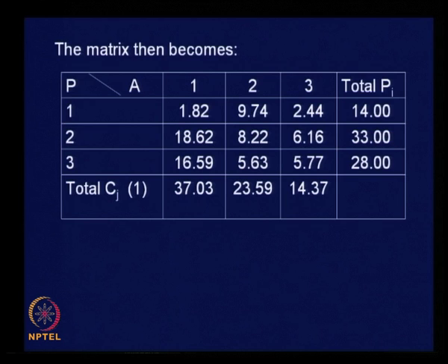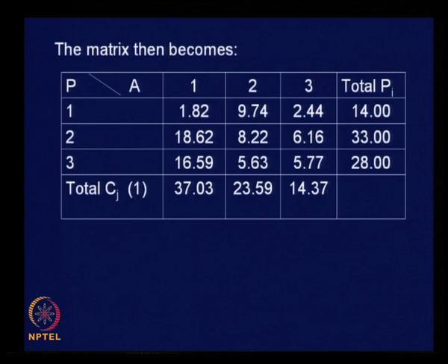Now what do we do with this result? Can we say that this distribution is acceptable? It is not, because the distribution process should not distort the basic values of trip production and attraction. Your zonal trip attraction values are distorted because of the distribution process. The reason is we have assumed a set of independent variables to be influencing the trip distribution and use those independent variables to get trip distribution.